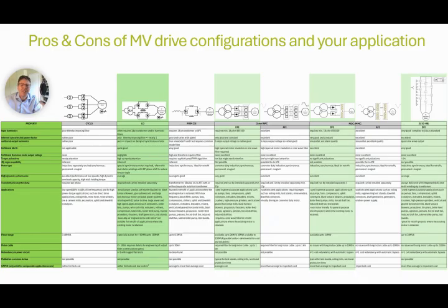The voltage source topologies require a parallel unit configuration to achieve such high power levels, compromising reliability and increasing costs. While most drives require screened motor cables, the predominant concern will be motor cable length. This parameter must be carefully considered as additional filters might be necessary.